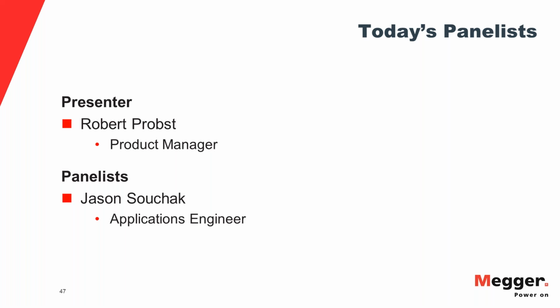Once the water trees get severe enough that they become electrical trees, the electrical tree will create a signal that we can detect, and that I'm sure will be covered in the partial discharge webinar coming up. But they are different signatures, different types of tests, and completely different phenomena, although they are related to each other. So no, to answer the question, the water tree itself does not have any characteristic signal injected into the cable. It's just the fact that it's weaker insulation at that point.